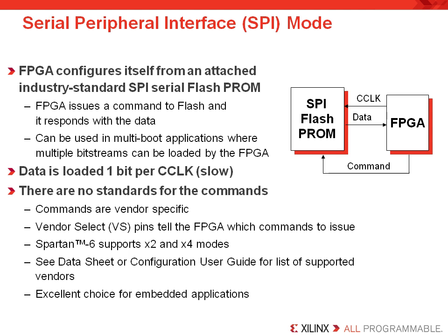Check the device datasheet for a list of the currently supported PROMs. Currently, these vendors include Numonyx, Spansion, Winbond, and Atmel. Users should plan on selecting a flash PROM that has sufficient size to contain the FPGA's entire bitstream. Refer to the configuration user guide for your device family. Find the size of the bitstream for your density of FPGA.